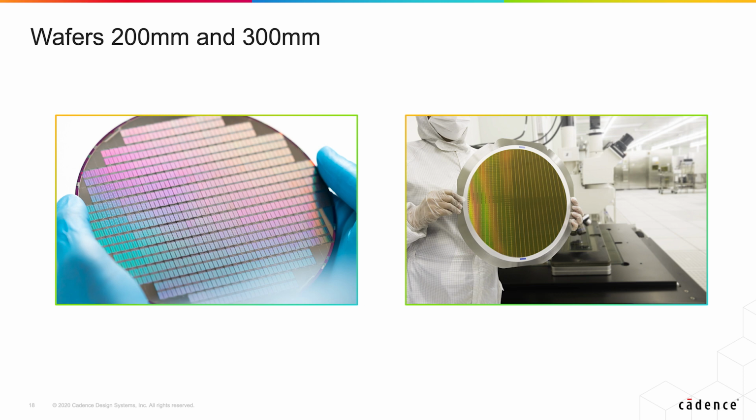And they're made in wafers, so we don't make chips one at a time. We make them on these wafers, and there are 2 sizes. Actually, if you go back far enough in time, there are even more sizes, but they're 200 millimeters or 8 inches, that's on the right, and 300 millimeter or 12 inches on the left. And then we put as many of the actual chips on there as we can fit, where you can sort of see the little square pattern on these chips, and each one of those little squares is a chip. Later they'll be chopped up and put into packages separately.